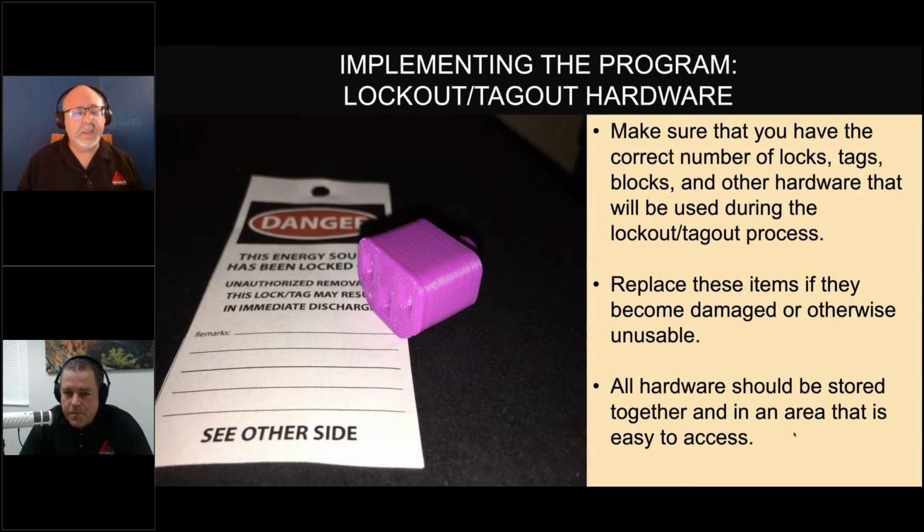Absolutely. Sometimes in my inspections, I go there and start looking at the lockout tagout station, and everything's missing. There's only a couple just hanging there, and there's no consistency in what's there. Then as I walk through the shop, I see a zip tie on the floor, and I ask, why is the zip tie there, like you just mentioned? Well, we ran out of tags. I couldn't find them. So this is a problem. We should be very careful, maintaining and doing management control with our product when it comes to lockout tagout hardware.